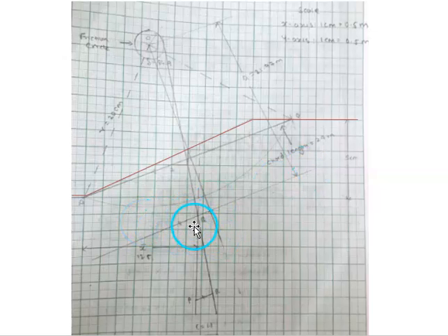Then from this intersection point, we have to draw a tangent to the friction circle, which represents the resultant reaction. So all these lines we have to extend like this, and then we have to draw a line by taking the W value to some scale. By taking the W value to some scale, we will be getting the load scale.